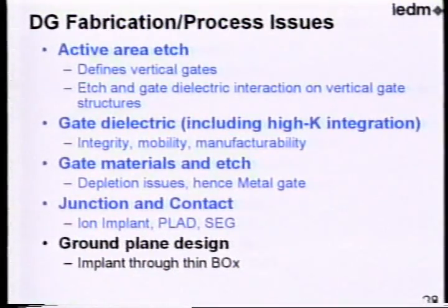You still have the issue of the very abrupt lateral doping that has to occur in this depleted area. It is also not trivial to get a very abrupt interface from the source drain junctions to the body.